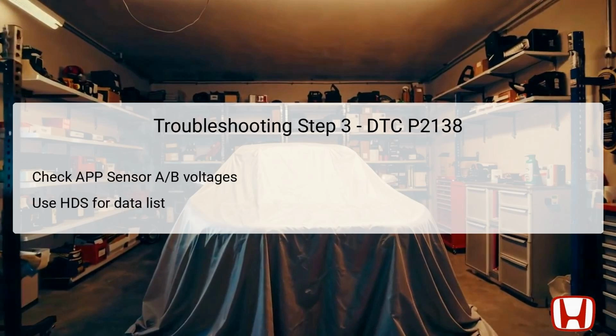In this step, the technician should check the operational voltages of APP sensor A and APP sensor B using the Honda Diagnostic System, HDS. It is crucial to determine if both sensors deliver the same voltage under normal operating conditions. Discrepancies in their output can point directly to faults in either sensor or wiring.